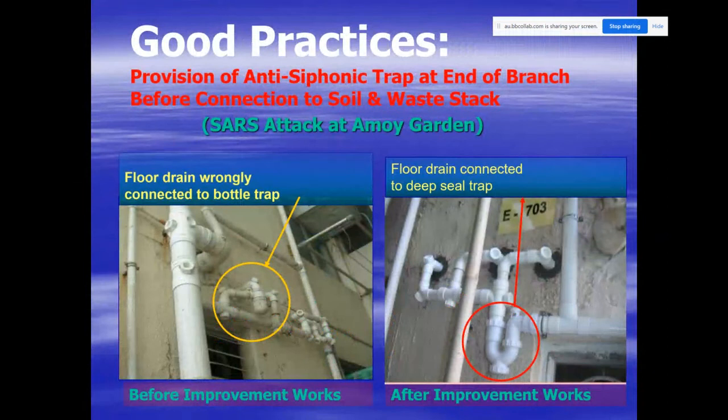Now, the one issue I would like to address is the drainage. Piping drainage is a design issue. If all the pipes are concealed in the pipe duct, you may get trouble. It's not easy to conduct maintenance if there is damage to the water pipe. For the drainage system, it is also necessary for us to conduct some maintenance, clean the drain pipes, cleansing pipes, whatever. So the location of the self-siphonage U-trap is the other issue.